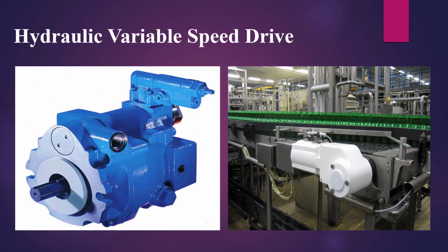Hydraulic VSDs are often favored for conveyor drive applications because of their inherent soft starting capability. In hydraulic systems, the motor or the coupling is managed by oil pressure rather than a magnetic field. It is this pressure regulation and flow control that allows for progressive starting and speed control. Hydraulic drives also tend to be more efficient than electrical ones in systems that require high torque in a small space. They are used in all types of transportation and earth-moving equipment because of their inherently high starting torque.